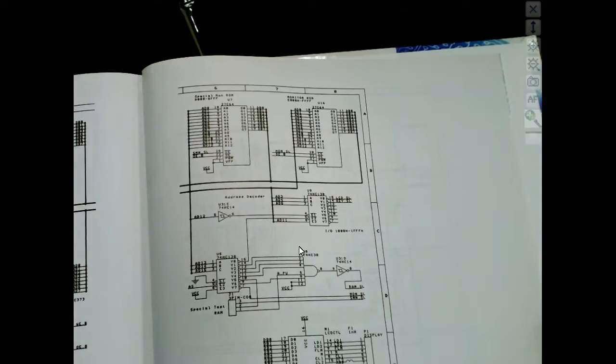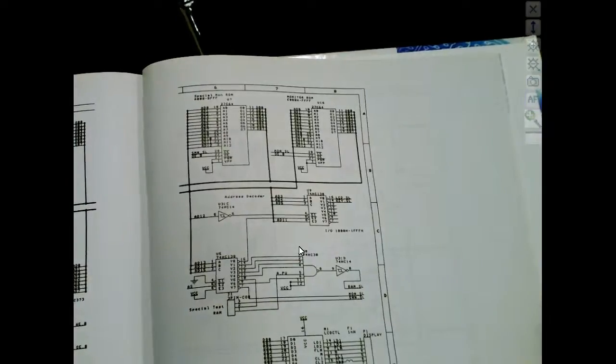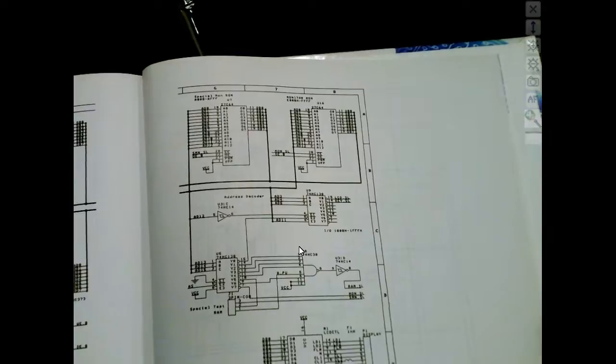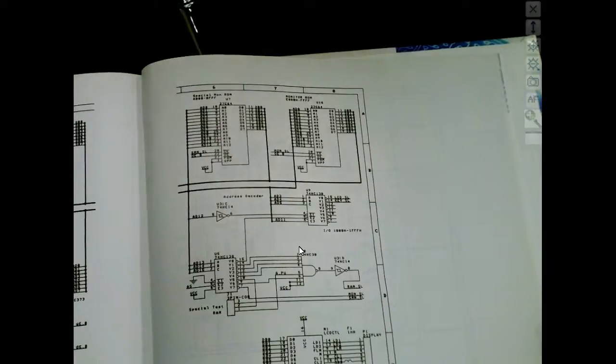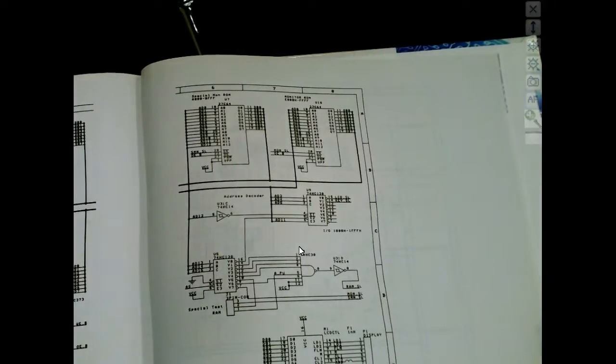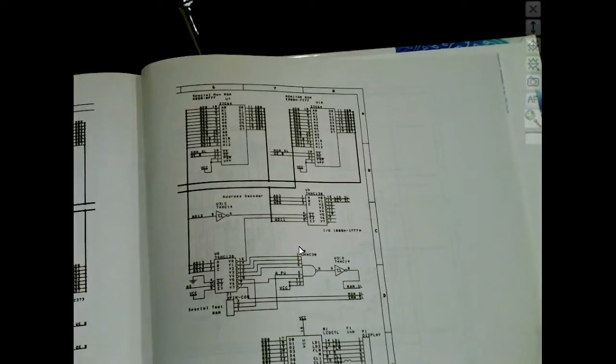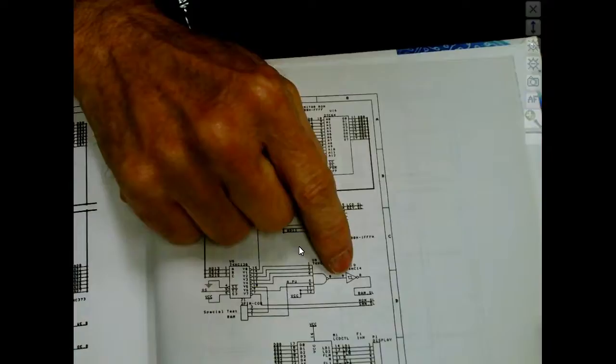Does that make sense? So the high threshold might be 2 volts, and the low threshold might be 1 volt. So if it sees it as a low, it's going to keep seeing it as a low until it gets above 2 volts. And then it's going to keep seeing it as a high until it gets below the lower threshold. So this is called a hysteresis loop.